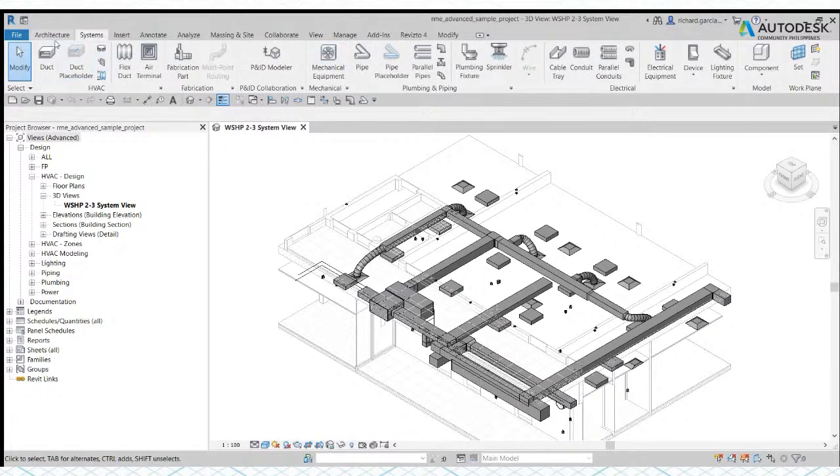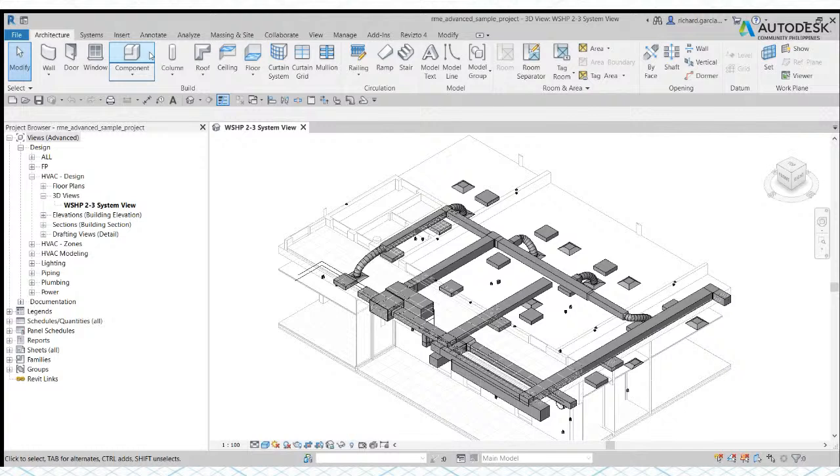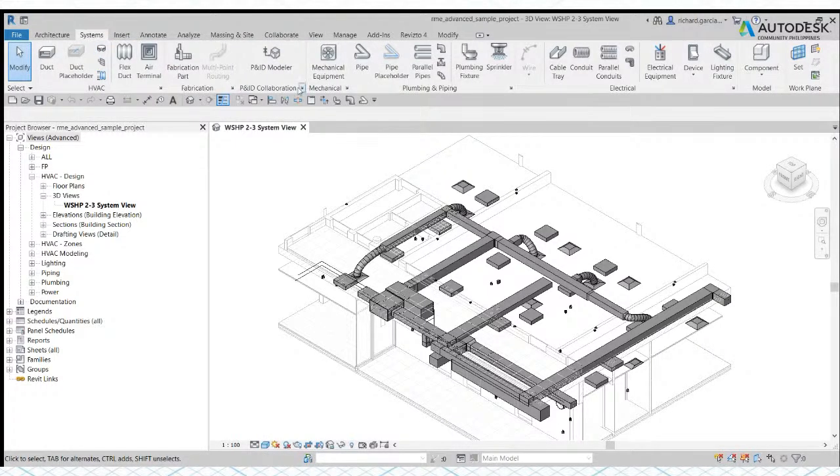So let's go back. This is our ribbon tab, these are the tool buttons, and you can also see some expanded buttons, just like in my device. If I click that one, as you can see, I can expand it. There's this drop down arrow, so you can click that. And then there are also some panels here. This portion here you call the ribbon panel. When I say, let's go to the plumbing and piping panel, that means it's here. This is the plumbing and piping panel.